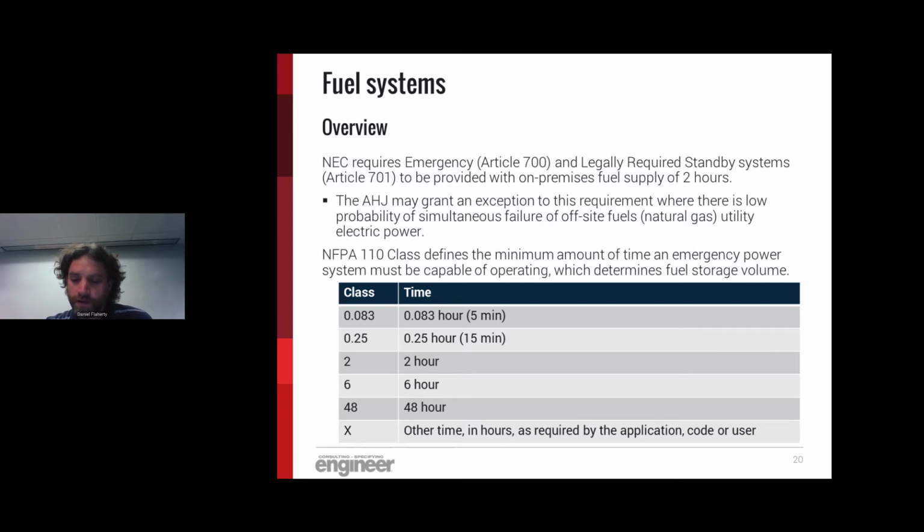The EPA typically allows 100 hours per year for maintenance testing and demand response. So anytime that you want to spend, you get 100 hours on an emergency generator to allocate towards that. However, if you go over that, then your system becomes less of an emergency generator and more of a power making generator, and is subject to tighter restrictions. However, you should check your local requirements when considering paralleling or peak shaving with your engine generator.